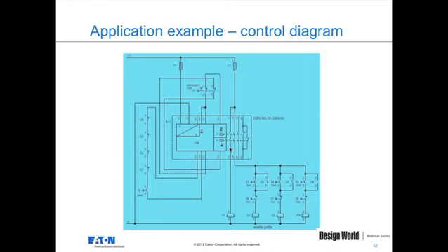So if any one of those contacts failed, the other one would still open and still interrupt power to this contactor coil right here. So this coil will represent the upstream contactor. We'll see that in the power diagram. And these other three coils here, wired with the start-stop circuitry, will represent the three downstream contactors. The upstream is on one path, the 13, 14, and the three downstream contactors are on another path here, 23, 24.